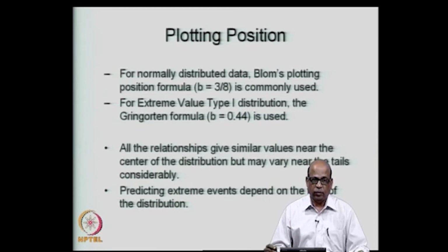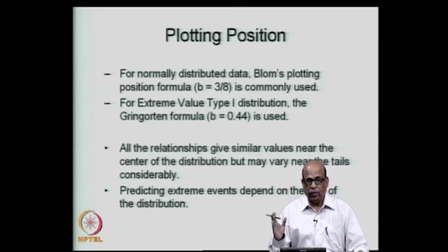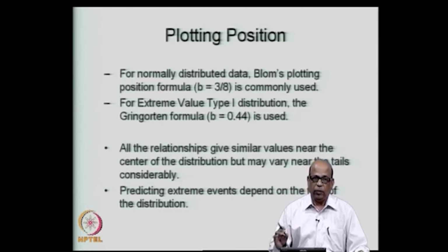And therefore, when you are dealing with extreme values, you must be specifically attentive to which of these several plotting position formulae that are available you would like to use.